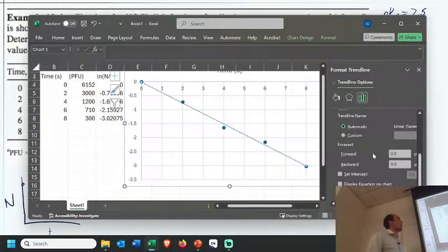Now, sometimes you might have a time delay before the first order kinetics begin. That actually occurs sometimes with disinfection if the bacteria have some cell membrane that's resisting chlorination for some time, or some other attack. Maybe you have some amount of time before we start inactivating at a first order rate, or the process begins. But we've got viruses here, and I don't see anything that would tell me we should shift this anywhere. So given that, I'm going to set that intercept to 0.